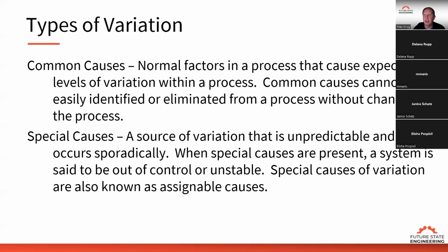So, we made a bunch of process changes. We changed the feeds and speeds. We changed the direction of the coolant. We changed the pressure of the coolant. I said, those are all process changes that we make when we have common cause issues. So you used common cause techniques to address a special cause problem. What's the chance that you solve this problem? They said, well, based on what you just told me, probably zero.